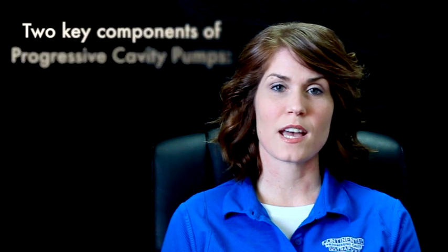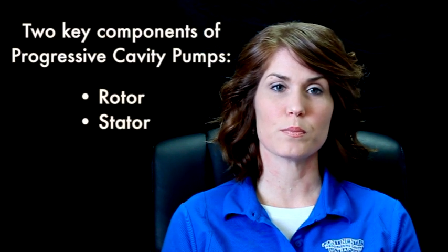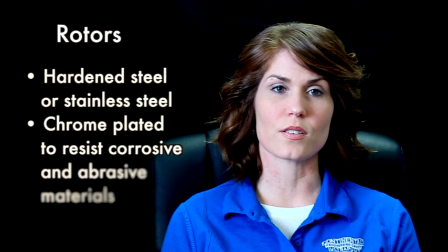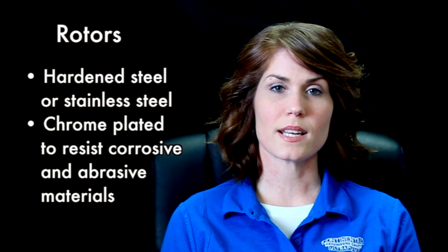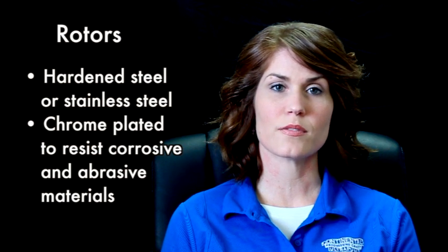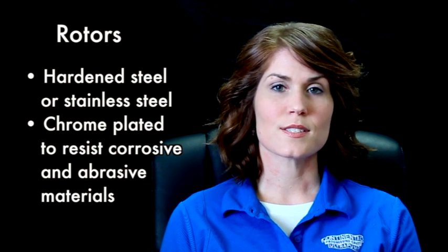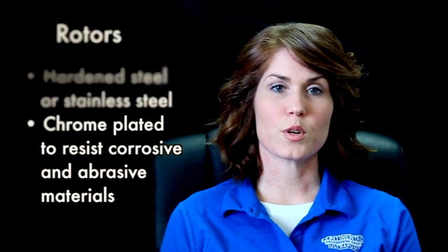Progressive cavity pumps have two key components which help move the fluid. They are the rotor and stator. The rotors are made of hardened steel or stainless steel and are covered with a chrome plating to gain resistance to corrosive and abrasive materials. Some types of liquid affect the chrome plating. In those applications, a non-plated rotor should be used.